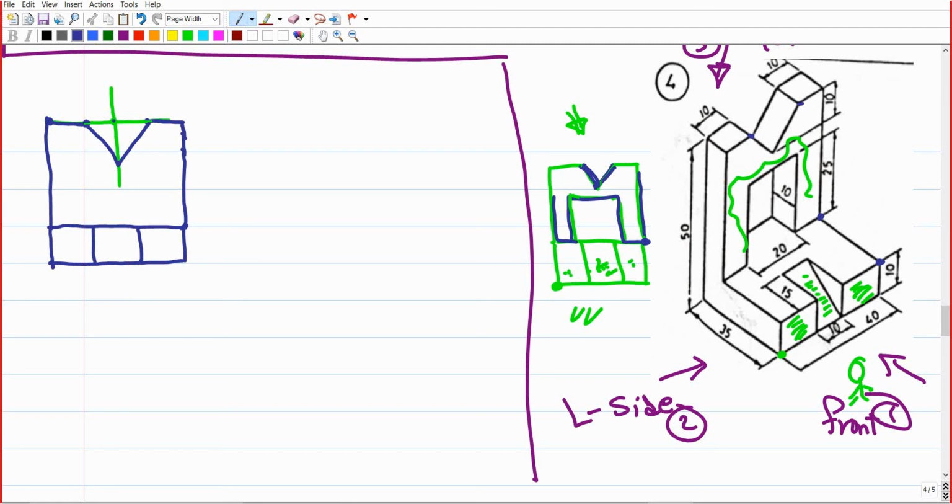Yeah, that's 1 centimeter. 10 millimeter is already one centimeter on the scale that you are already using. Okay. And also for this one, it is 20 millimeter. This gap, it is 20 millimeter, and this height, it is 25 millimeter. So from this center point, you're gonna measure 10 to the right, 10 to the left. Then you're gonna go up with 25. Then you're gonna close the shape. Make sense? Right, so this is for the front view.